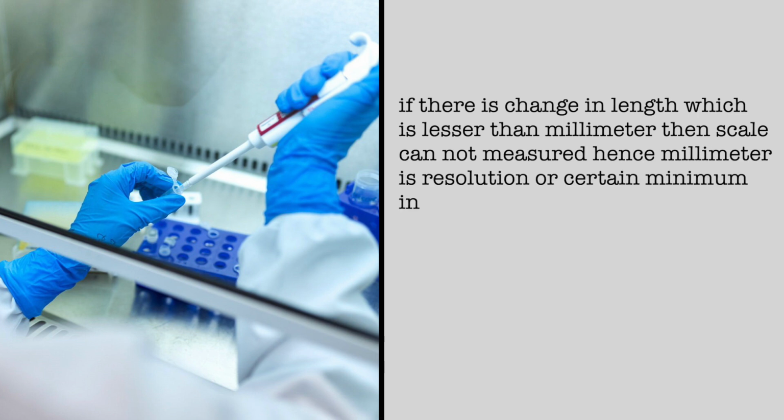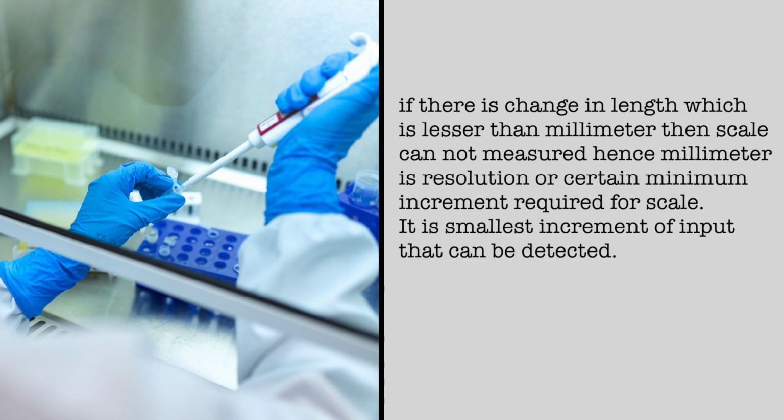Suppose we are taking a scale and measuring length. If there is a change in length which is less than a millimeter, then the scale cannot measure it, hence a millimeter is the resolution, or certain minimum increment required for the scale. So it is the smallest increment of an input that can be detected.